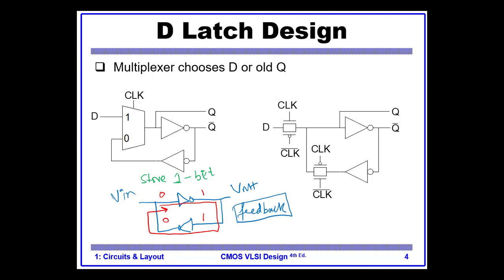Now let's move to an actual circuit of D-Latch. The actual circuit looks like this one. It has a 2x1 mux, which you have studied in the previous lecture, and then we have a NOT gate, and then we have another NOT gate. It is connected to one of the inputs of the mux.